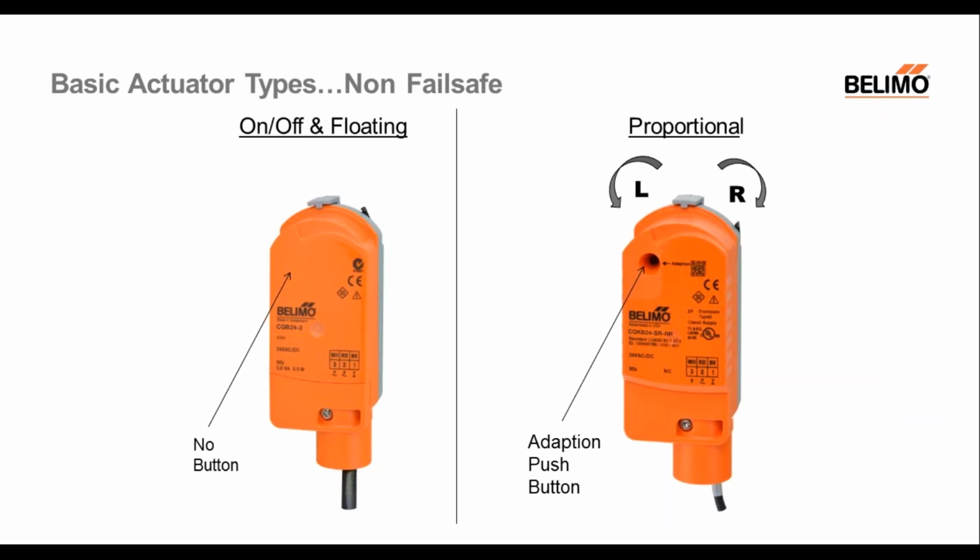On your on-off / floating point actuator, once you've changed that clip position to a new angle less than 90 degrees, you will need to know what is the run time from 0 to that new angular position. This is included in the flow setting capacity tool as we saw before, but it's also included in the supply documentation that comes along with the valve assembly.